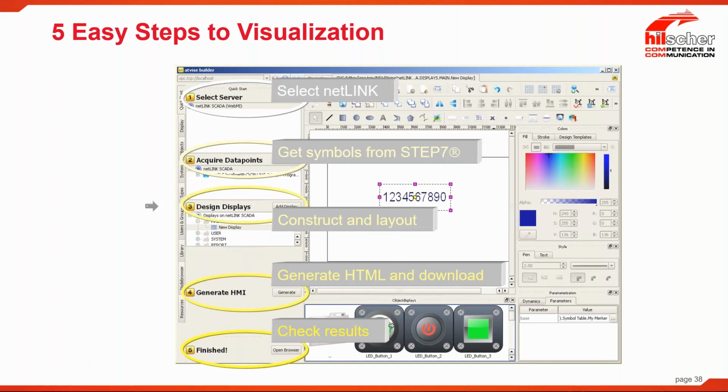So things such as valve positions, tank levels, start, stop, alarms, those types of things are all possible through the software itself. Then at that point, you generate the HMI. You generate those pages in HTML, which is done through the software, and then you publish it and you're done. Literally then at that point, it's accessible via an HTTP page.